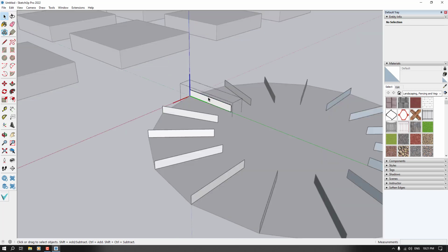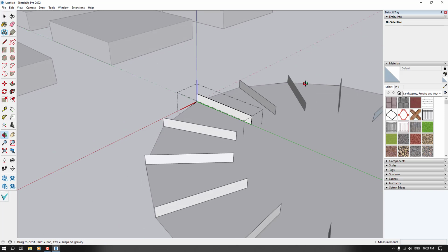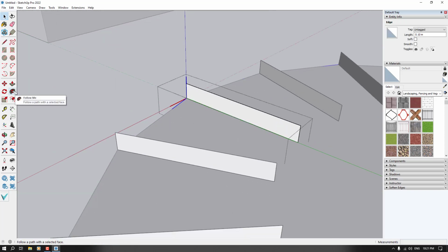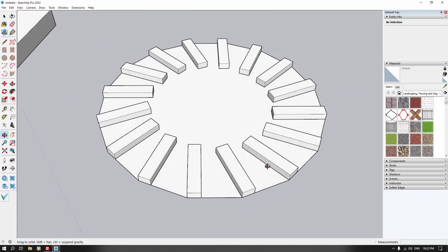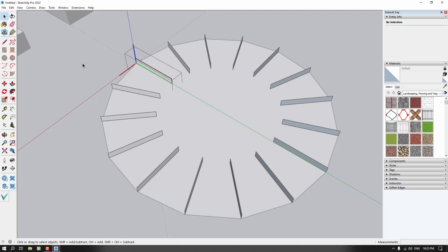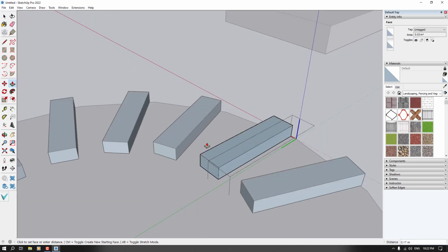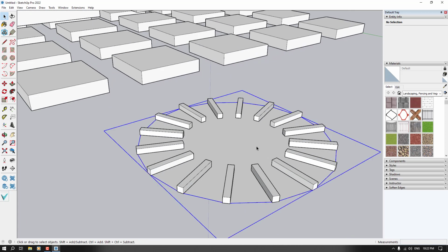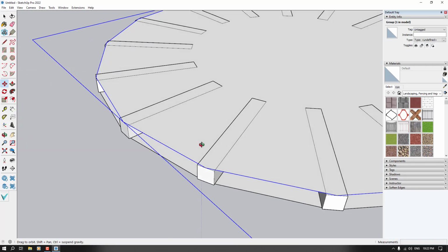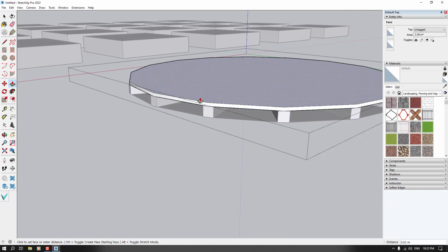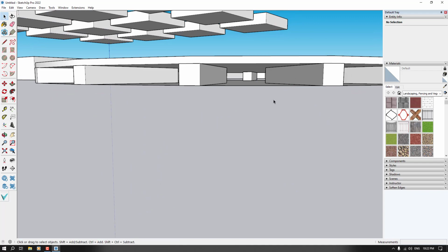Now you can click on one of them, you can draw some line, something about 10 centimeter, as you can see. Now you can click on it, use follow me option, and create it. As you can see, we create this type of model in SketchUp very simple and easy. Sometimes you can press Ctrl Z and only extrude your model, something like that. For example, 3 centimeter from this place and 3 centimeter from this place again, and this is your main model in here. You can take another copy of this face, for example something like this, and now you can open it and give some extrusion about, for example 2 centimeter for it. As you can see, now we model some type of wooden pallet.